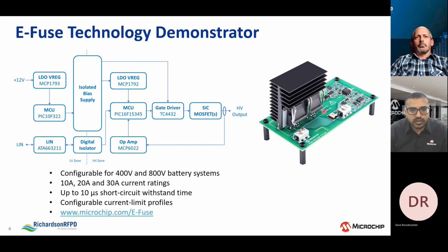Now, this design is available online. If you visit microchip.com/eFuse, there you can find all the design files for this. So the Altium design files, you can get the Gerbers, you can send them out to get built. You have the schematic, the build materials, and the software as well. And a user's guide too. So the user's guide has a lot of detail on the design and how to design an eFuse or solid state circuit breaker application for DC systems.